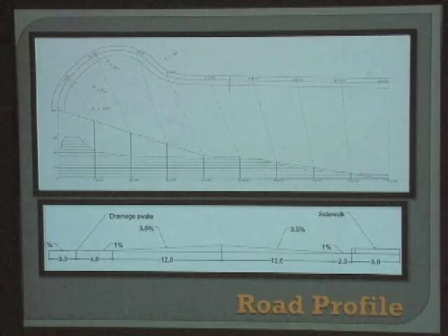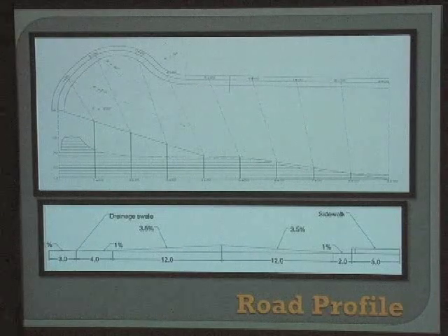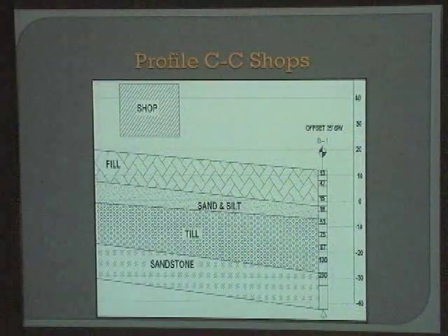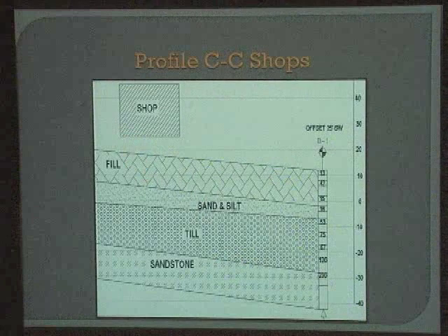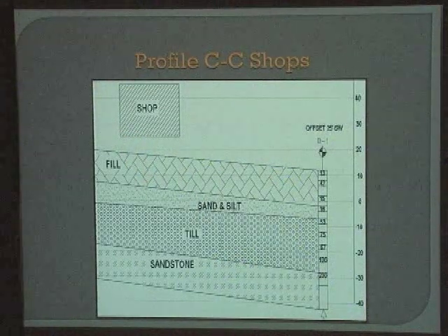And about this, we recommend bituminous asphalt binders, which is 3/4 inch stone, and bituminous asphalt top of 3/8 inch stones. We're also taking advantage of reclaimed asphalt products. That's our road profile, and Sam Jacobs will be talking about the geotech aspect of our presentation.